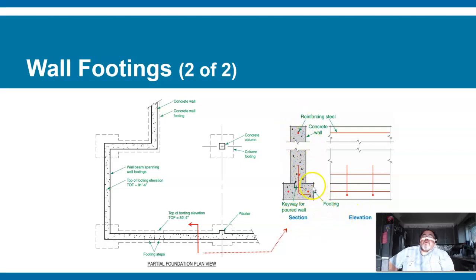So as you can see, here's the footing, the concrete wall, the red reinforced steel. Here it's showing you the elevation going sideways. Here it shows this way on the left. It shows it going like this, straight at you. And then on the right, it shows what it looks like from the side as it goes from left to right. And here are the steel bars every so often. That's these guys in the L-shape.